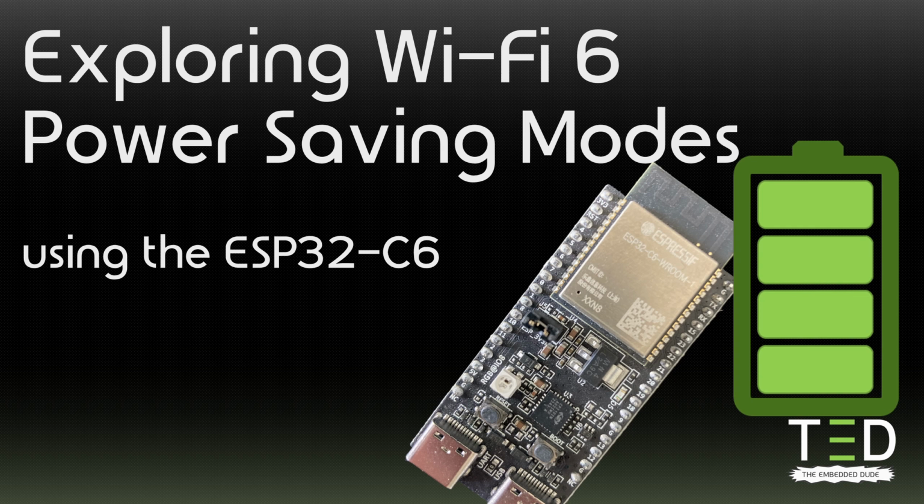In earlier videos I have been talking about the ESP32-C6 and its Wi-Fi 6 power saving features that are supposed to benefit battery powered Wi-Fi devices. For this video I made a little application that uses the ESP32-C6 dev kit and a few sensors, which I'm using to explore how much power we consume using Wi-Fi 6 power saving modes compared to the more traditional Wi-Fi power saving modes.